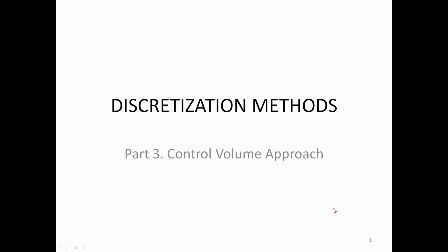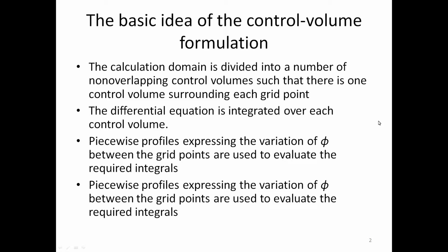Often, elementary textbooks on heat transfer derive the finite difference equation via the Taylor series methods and then demonstrate that the resulting equation is consistent with the heat balance over the small region surrounding a grid point. We have also seen that control volume formulation can be regarded as a special version of the method of weighted residuals. The basic idea of the control volume formulation is easy to understand and lends itself to direct physical interpretation.